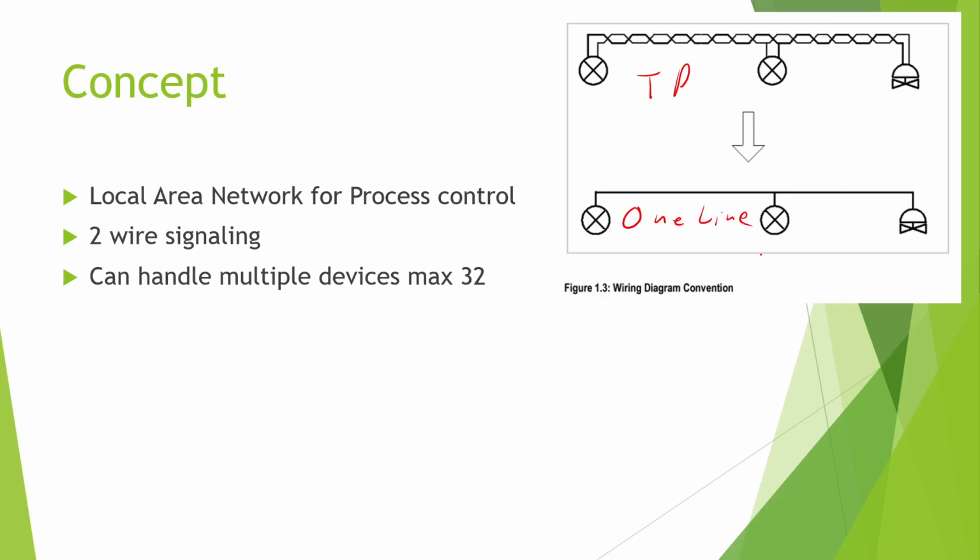All right, now this can handle up to 32 different devices. Right? And my notes say that is 32 devices that are not bus powered. It means they're not all sharing the same power supply kind of way. If you are going to have everything be bus powered, you're limited to 12. So something to think about. You also, if I say the word intrinsically safe, what does that mean?